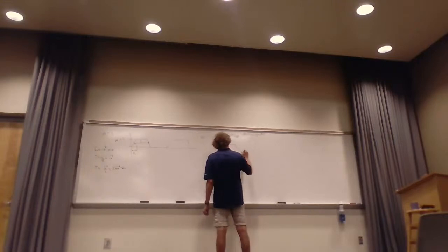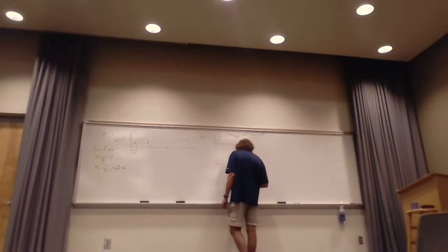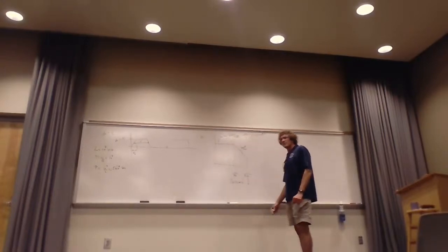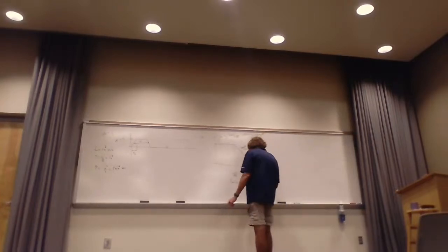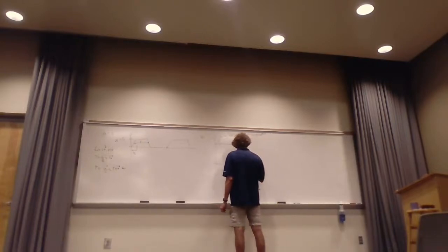Then it starts falling off at minus 20 dB per decade until you hit 1 over pi tau rise. 15.96 or something, 93? 15.93 or 6? I kind of rounded, so, yeah, I put on 15.9 megahertz, all right? And then it starts falling off at minus 40 dB per decade. And this is what it looks like.